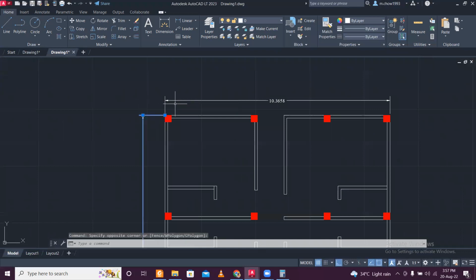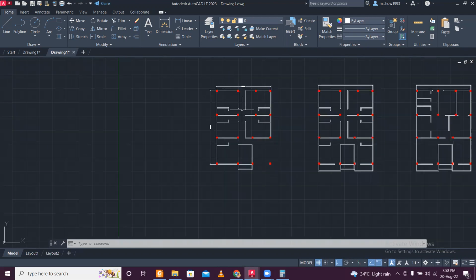So once we have known that this is accurate, the next thing which we need to do is make the beam column plan, because in STAAD.Pro, when we see the beam column plan, we need the exact location of the beams and columns. Since we have three different types of drawings in three different parts, we'll not import the CAD file. We can import the CAD file and then do the first floor plan separately, but we'll make these nodes, and then we'll proceed. So there is no problem in that.